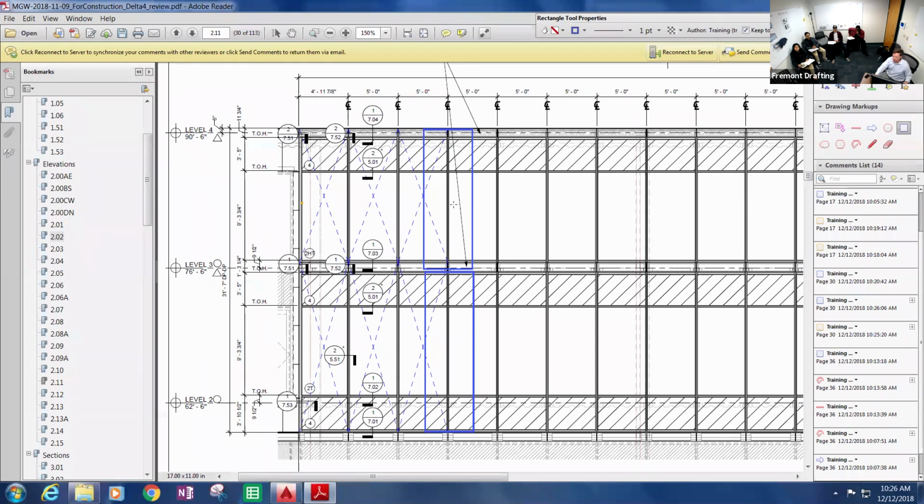It doesn't change the wind load going to that, because my wind load was already skewed up. But when we look at the dead load, and then the other half, the wind load would be up here, just like it is on this one already. So the only time that really happens is when we come up to a soffit or something like that. I don't actually get to a floor where I can have a Mac anchor and put the dead load clip up there.